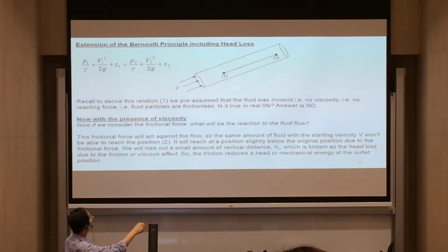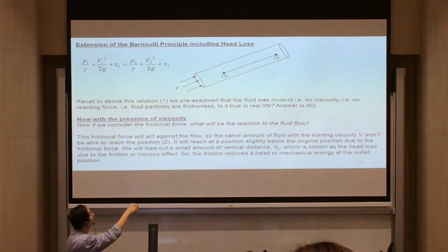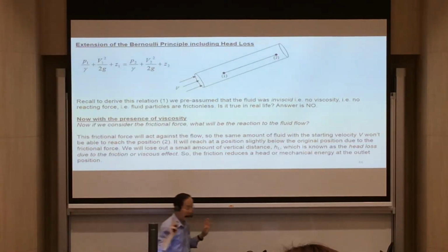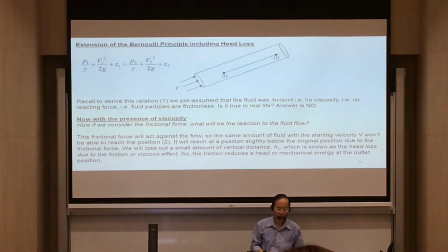This is a common datum. So from there to there you have Z1, from there to there you have Z2. It's not from here to there and there to there. In this case Z1 does not equal Z2. Normally you are given a common datum, and that is your Z1, and that is your Z2, so Z1 minus Z2 is not equal to 0. Be careful with that.